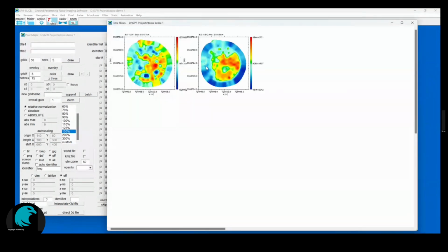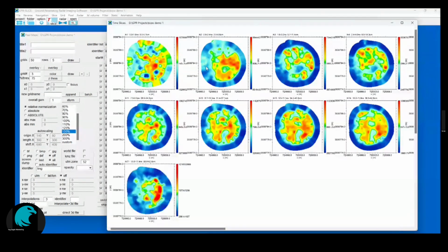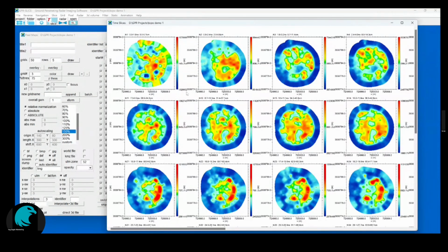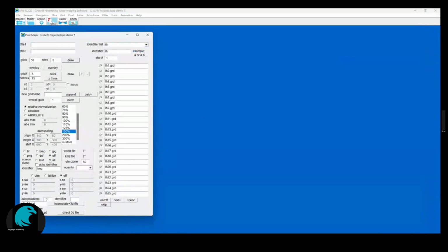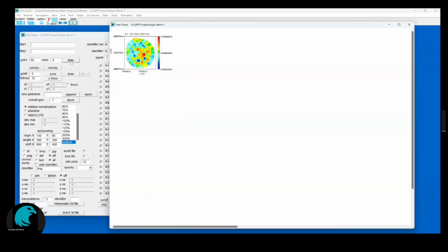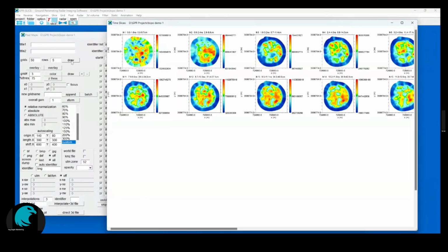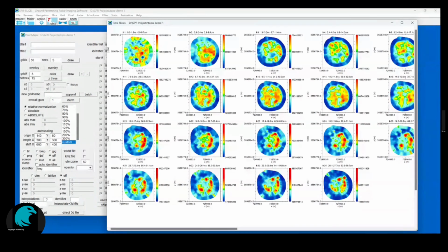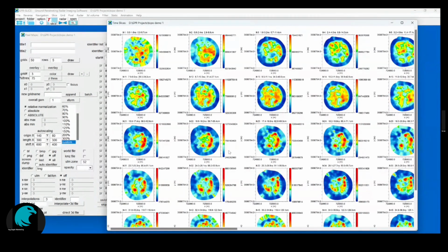Let's redraw it. And what we could do is I have numbers on the color bar here, and they're 32-bit numbers. We're going to have to do just a little bit of custom displays here. I'm going to make each map 300 pixels, and I'm going to shift by 600 pixels in X and Y. So this will allow us to look across the data here and see the numbers on the color bar.